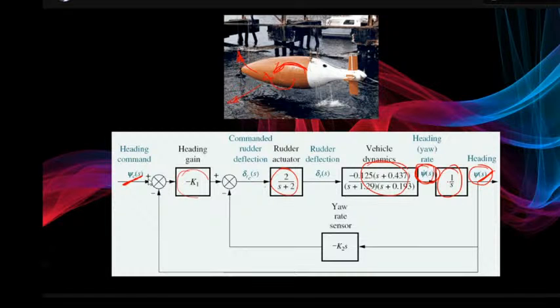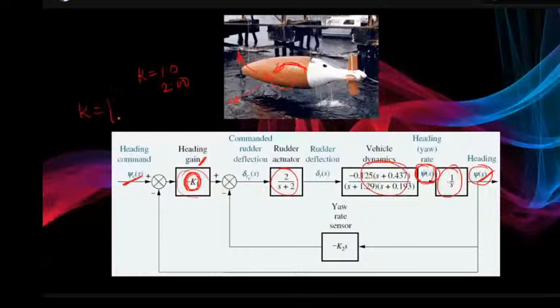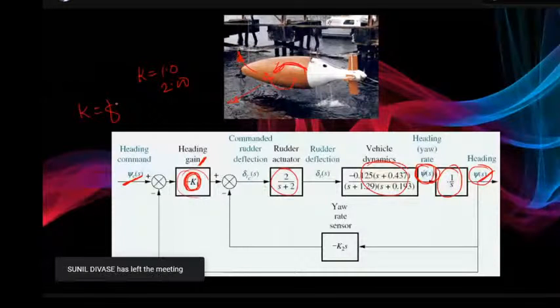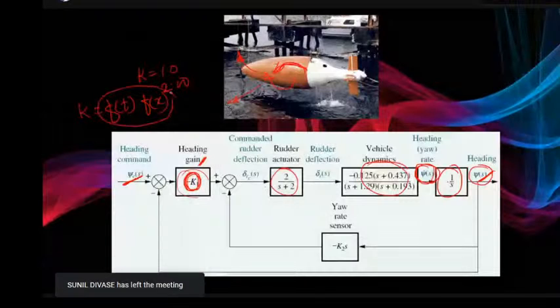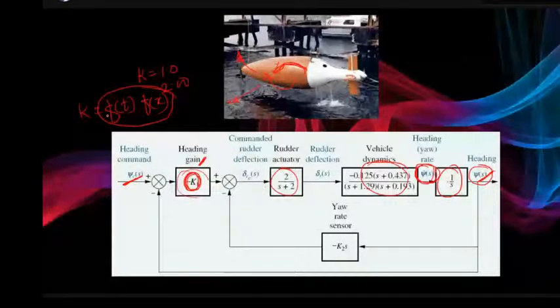Once you design, then you look at changing the design of the system by changing this parameter, the gain parameter. In a control system, this gain may have only one single number, maybe 1, 2, something. This K may be some function of time, or a function of some position. So this is called the control law of your system. What is the way it behaves? What should be the behavior? That is what is decided by these laws.